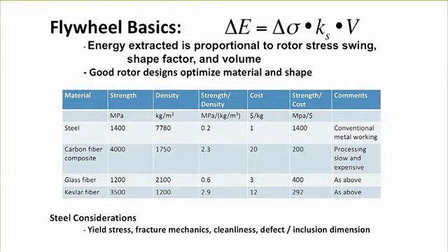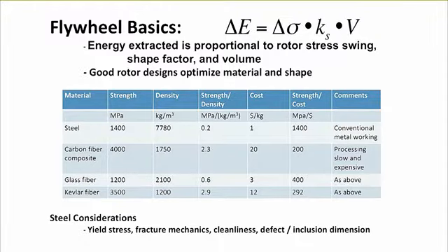But once you get to that, you quickly look at that complicated chart I have, and the thing that I probably ought to optimize is the strength to cost, if it's otherwise all feasible. The next to last column on the right is the strength to cost column, and steel seems to be the dominant animal there among the other materials. When I mentioned vehicular applications, some of the first people who looked at the possibilities said, I'm going to use carbon fiber.